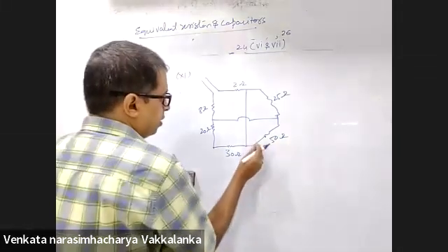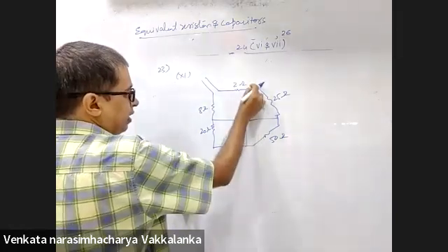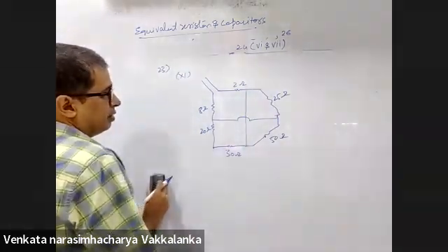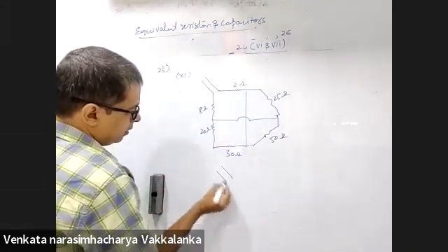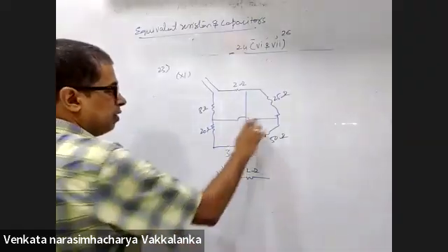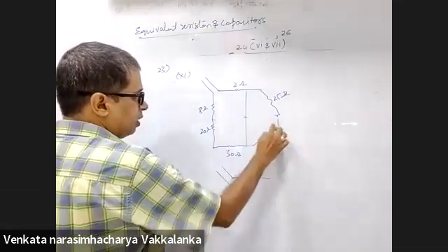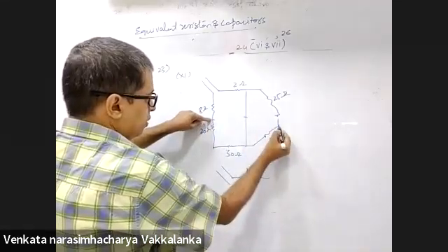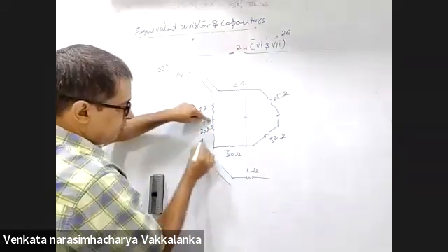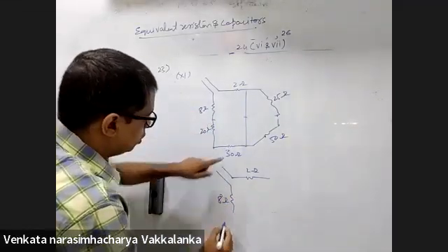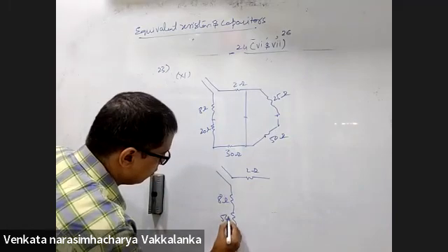Right? Now, I can take this point here and this point here. Now, when I do that, 2 ohms. Have a look at this. This junction is nothing but this point. This point should be placed here. These both are in series now. Do you agree with that? Yes, sir. This is 8 ohms. 20 and 30 are 50 ohms.